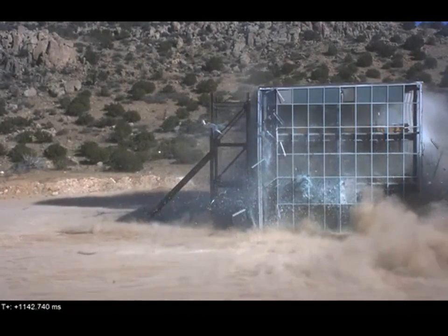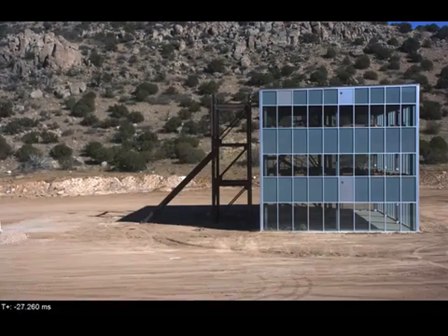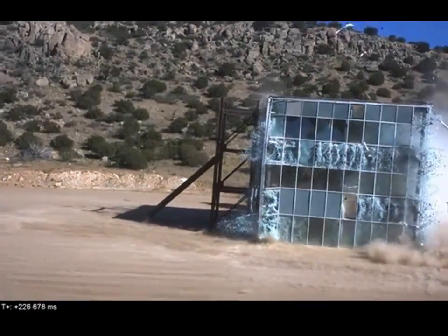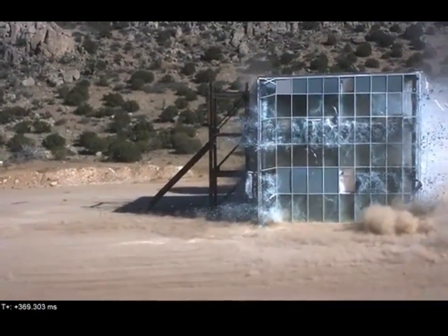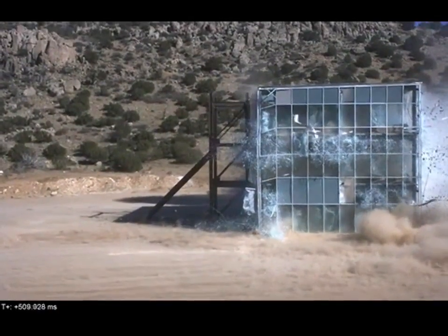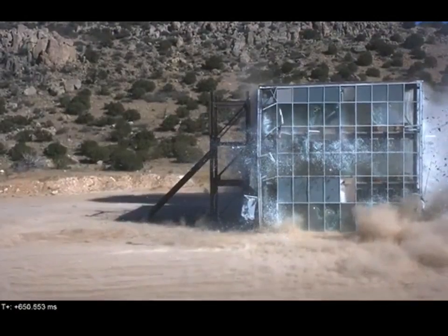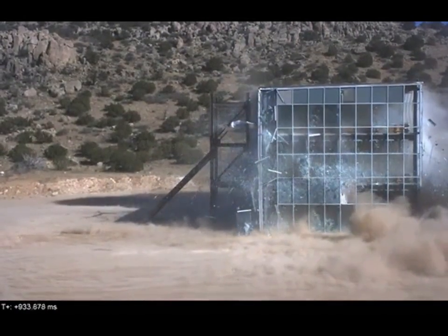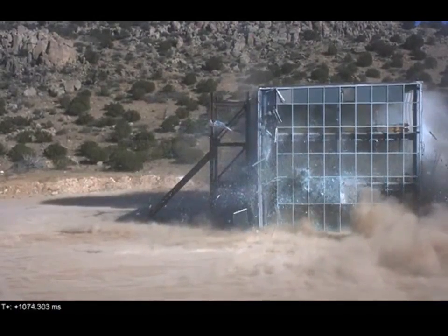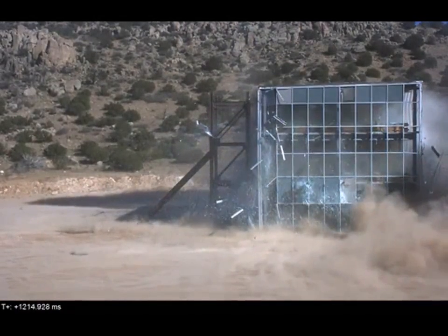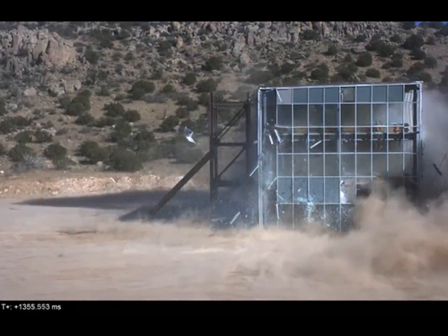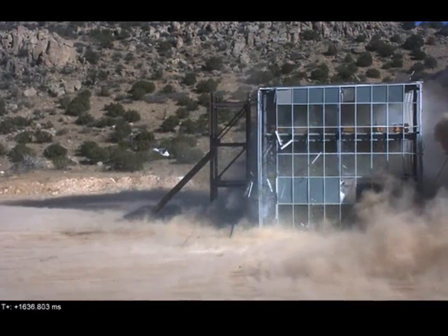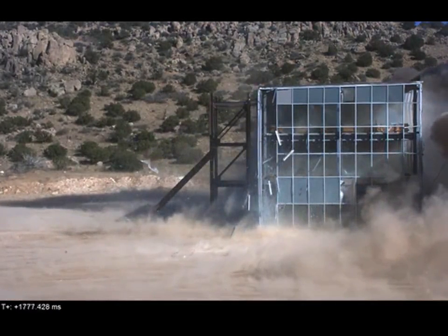The next item that I wanted to bring up as we look at this video again is the fact that in order to load a component, the component needs to have a member that collects the load and transfers it to the member. As you notice here, the facade or the envelope of this building was not hardened, so it fails really quickly. And when the blast load enters the occupied space, there is no significant damage to the members. That's because none of them have collecting elements that were collecting the blast load and transferring it to the members.